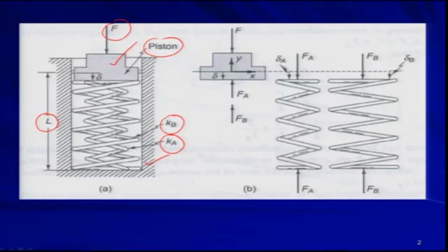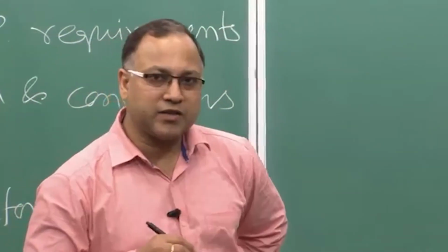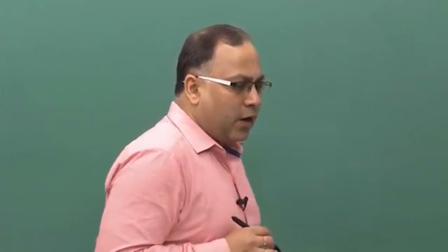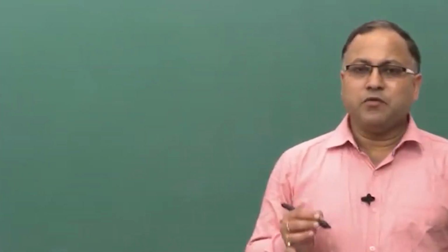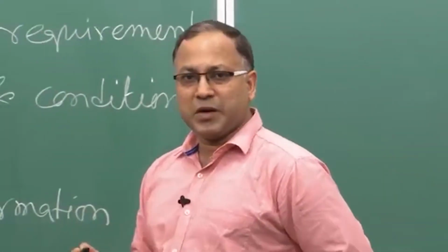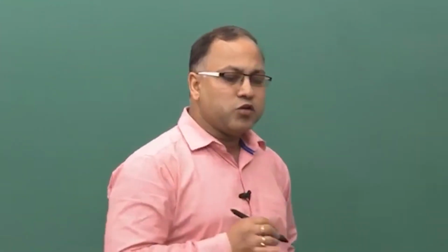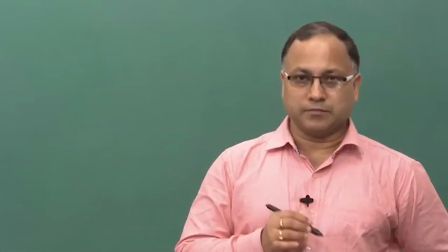Now, from your intuition or concept, what will happen if you apply the force F on top of this piston? The piston will try to push the spring in the downward direction. So, if you try to draw the free body diagram for the piston as well as for the springs, how will it look? Let us first draw the free body diagram of the piston.